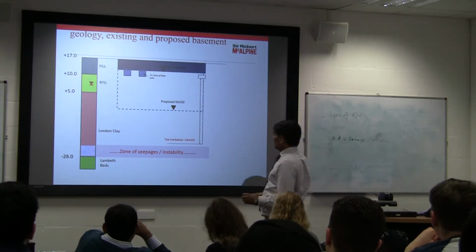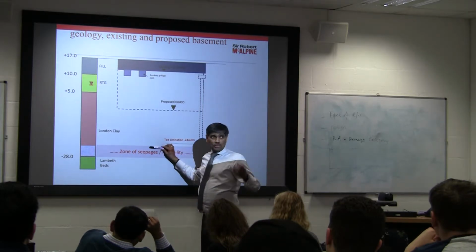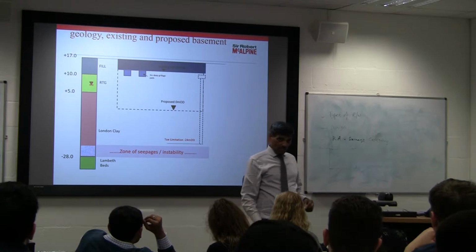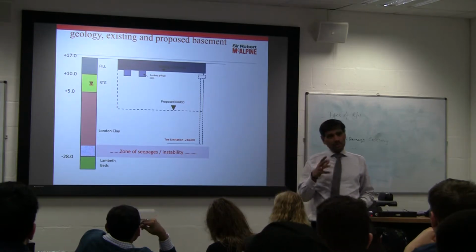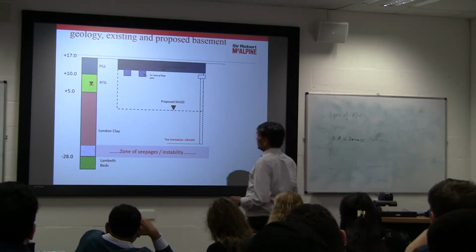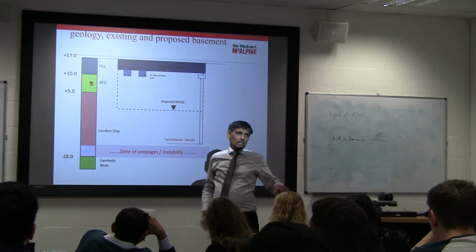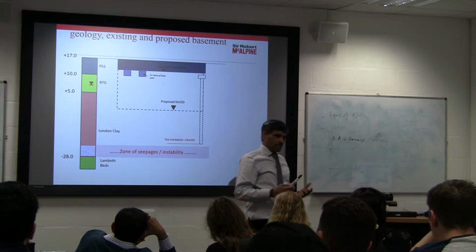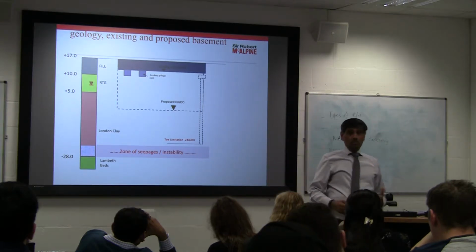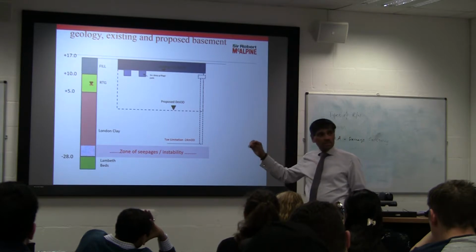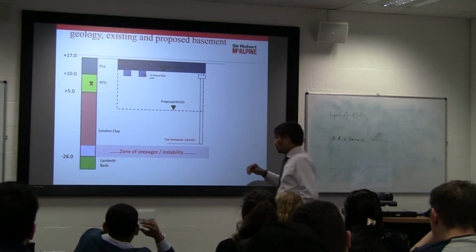And also, when you go to the formation, you can see the site, what material we are bearing on, what material we are dealing with, how we deal with it, all the aspects are taken care of. In this particular scenario, you can see we've got terrace gravels and we've got London clay, a lot of obstructions on site, and that bottom-up construction gives a fantastic, safe approach to construct that basement. That is the reason we chose it.